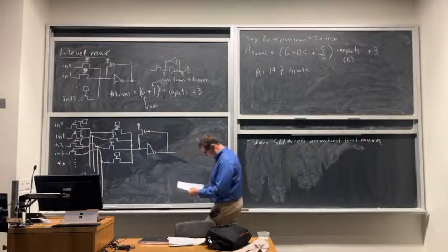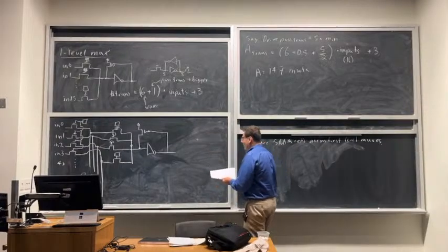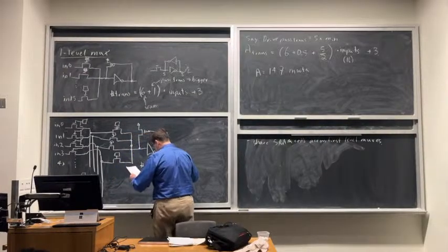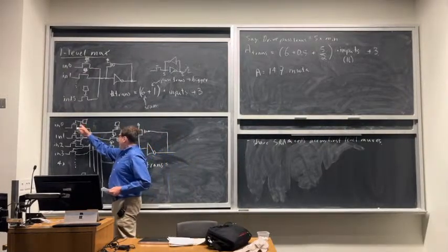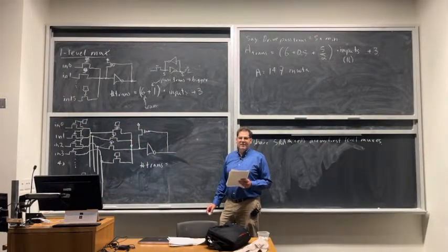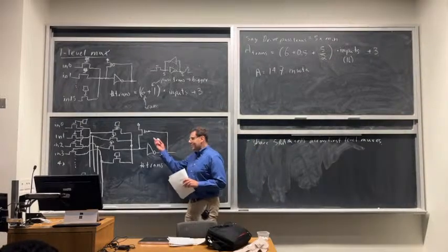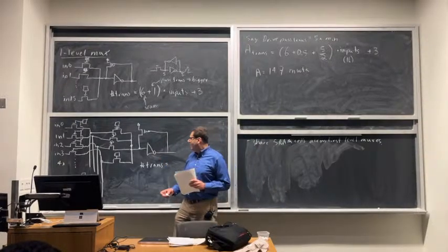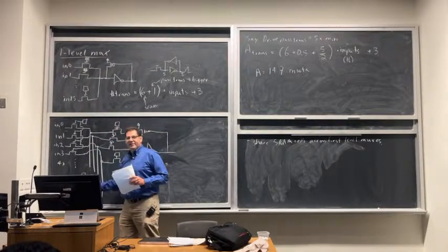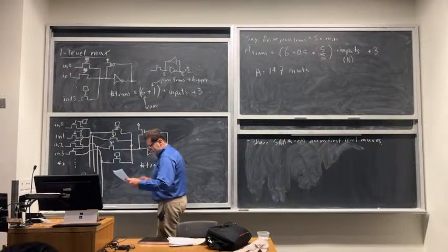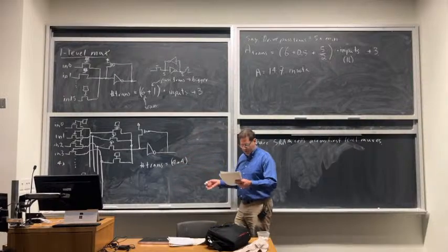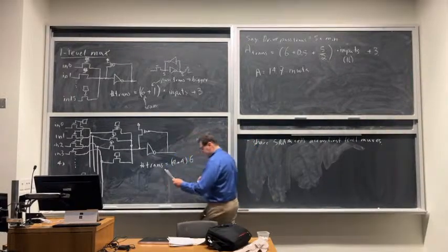Okay, so let's see how well this one works. The number of transistors is equal to, okay, SRAM cells. How many SRAM cells do we need in this for a 16-input mux? It's like a test to see if you're following me. So how many SRAM cells in total in this? I drew 4 here, so it's at least 4. So how many are in this stage? 4, right. So there's 4 in this stage, 4 in that stage, so it's 4 plus 4. It'll be slightly different numbers for different numbers of inputs, but for 16, that's the right answer. So that's your SRAM.